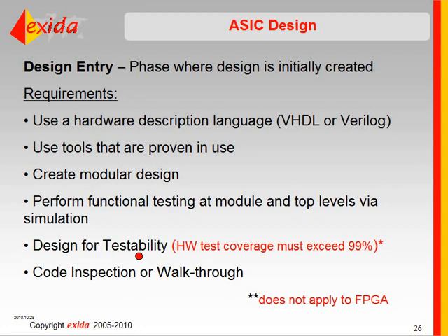in the final part. So essentially, the final part needs to have a 99% hardware test coverage, meaning that 99% of all faults where a gate would get stuck high or stuck low need to be detected in the final part, so you can prove out the final part at the end once it's been manufactured. And so in order to meet such a high level, you obviously need to design that in up front.